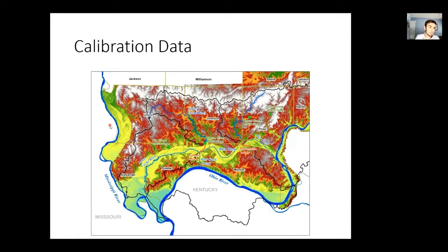And we also had a lot of data to use for calibration. We had 4 USGS gauges spread out across this modeling area, most important of which being the Cache River USGS gauge just north of the Karnak River. We also had high water marks that were collected throughout the lower Cache River and some along Main Ditch as well. And then we also had flood aerial imagery that was collected for this 2008 flood, which was interesting to work with and make visual comparisons for our modeling effort.